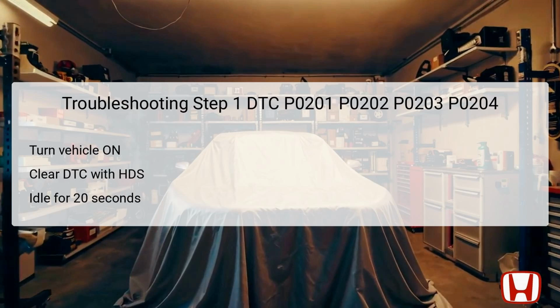The first troubleshooting step is all about verifying the problem. Start by turning the vehicle to the on mode, but do not start the engine just yet. It's crucial here to clear the DTC using the Honda Diagnostic System, HDS, which resets the system and allows you to gather fresh data. After clearing the codes, start the engine and let it idle for approximately 20 seconds.